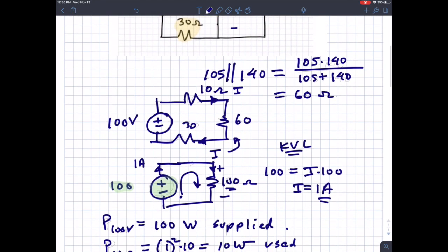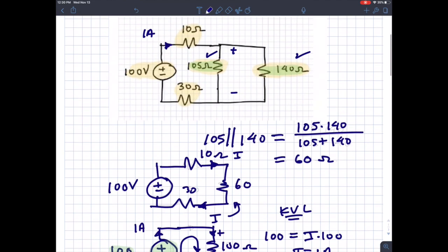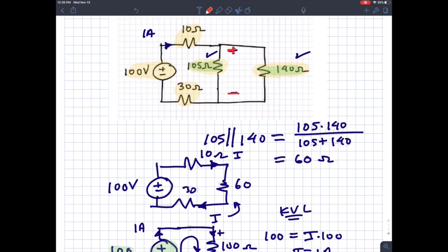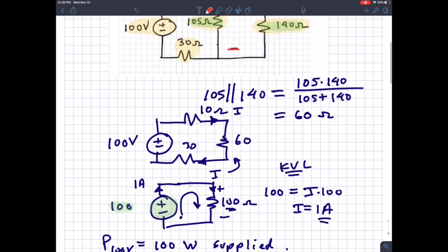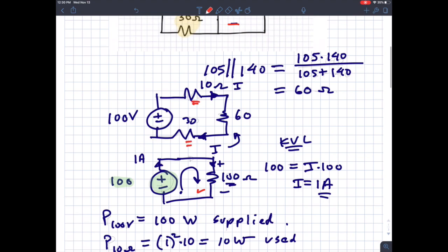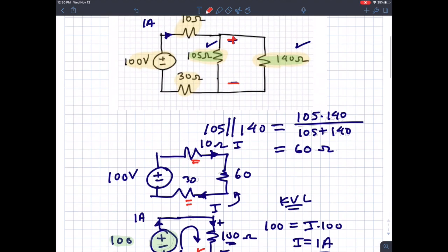So where is that voltage, the part in red, on one of my equivalent circuits? I can't use this one because those two resistors got absorbed in, and I'd lose those points in the circuit. But between these 2 points, I know this is the equivalent voltage that shows up in the first equivalent circuit.